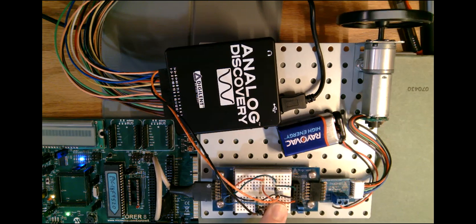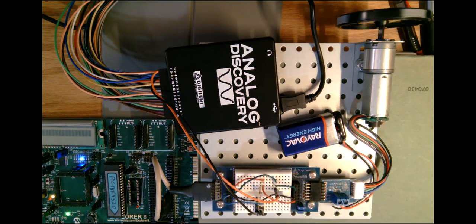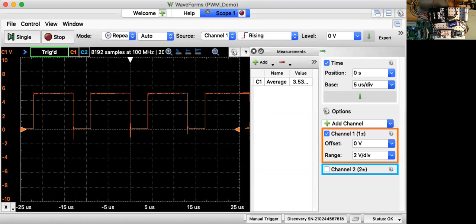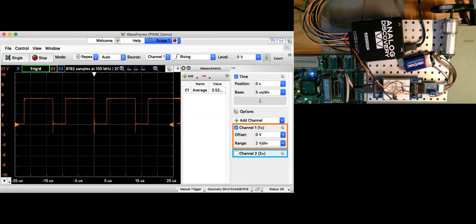Now, if we take this orange wire that's coming up into the analog discovery, I can share the analog discovery up on the screen here. Hopefully we can still see the wheel going around in the corner. So here's my orange wire being graphed over here on the analog discovery. We can see that this waveform is on a whole lot more than it's off.